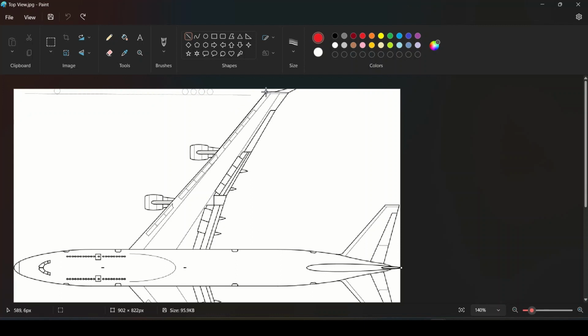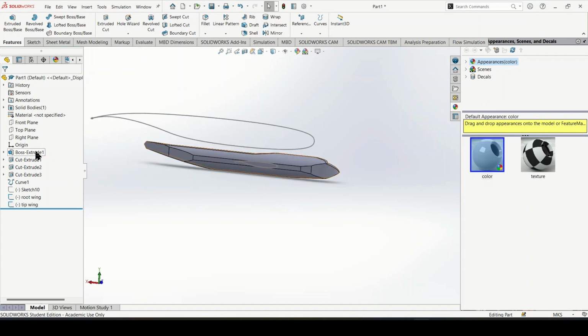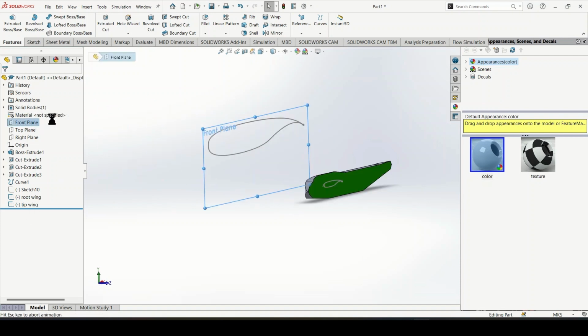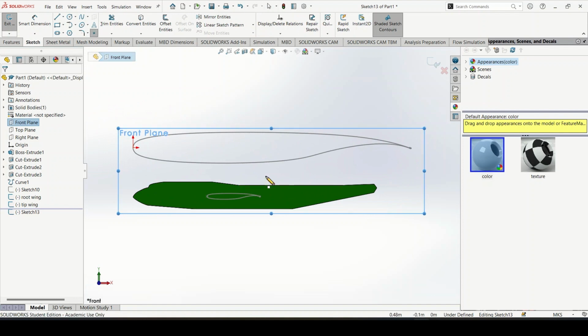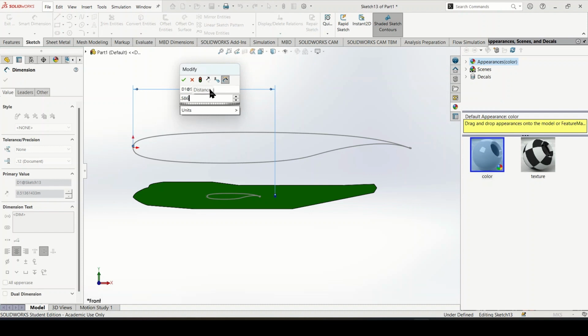We can see here that the tips go from pixel 586 to 639. That is 53 millimeters, and again, 586 is our starting point. So create a sketch on the front plane. We also want to make sure it aligns with our middle point here, but it will be farther back, 0.586.